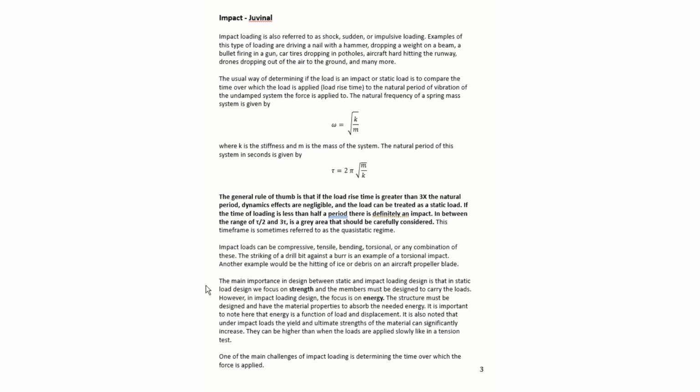The main importance in design between static and impact loading is that in static load design, we focus on strength, and the members must be designed to carry the loads. But in impact loading, we're not so focused on strength, but we're focused on the system's ability to absorb energy. And it's important that the system be able to absorb that energy instead of have a super high strength.